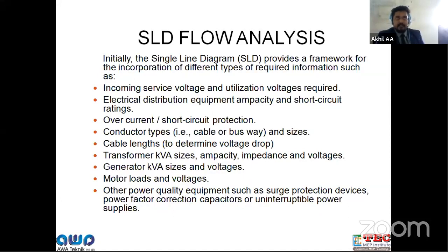also the generator. Based on our backup load, the generator will be provided, so it will be shown in the SLD. So you need to show where this generator supply is going, like you will be providing a generator main switchboard. This generator main switchboard might be connected to the backup load that we require in the particular building. Okay, and the motor loads, the building will be having certain motors like lift motors, water pump motors, and additional lift motors, everything.